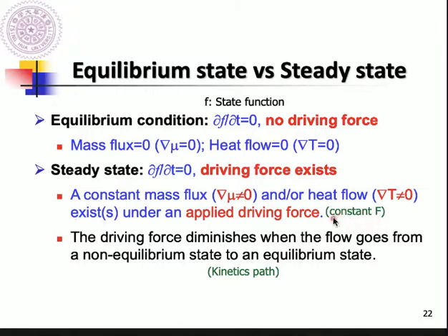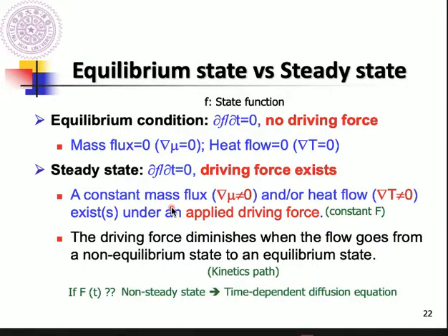Some people ask, is this a constant driving force? So we got the constant flux. How about a time-dependent driving force? Then we will get the non-steady state. Non-steady state just tells you the differential equation will be time dependent. That means the concentration or the temperature distribution profile varies with time.